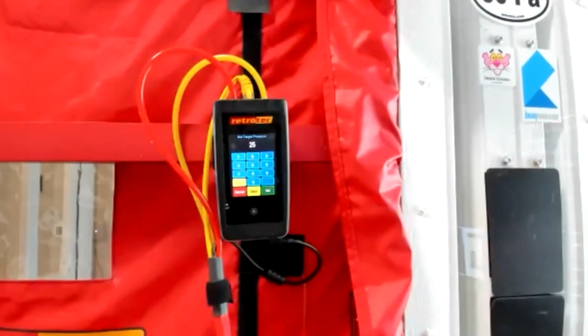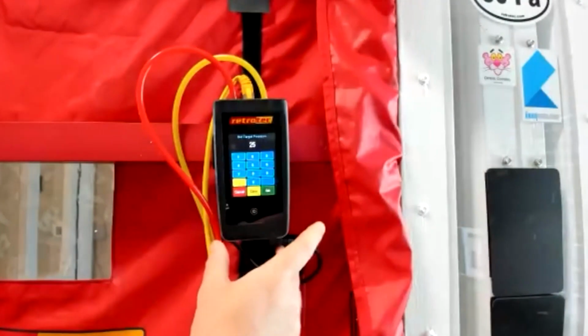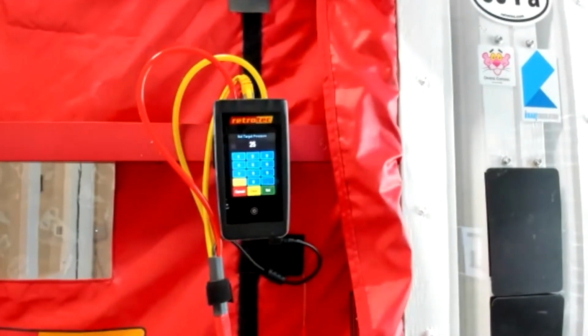Again, I want to start at 25 and then walk around and make sure nothing's getting disturbed, or I'm not noticing any funky smells or anything like that. Sometimes if you test homes that haven't been occupied for a while, the P-traps for the sinks or the washing machines or whatever don't have any water in them, so you're just pulling in sewer gas. If that happens, you'll know it immediately. It smells awful. That's happened to me a few times. So just make sure you have water in the P-traps. You can just run a little bit, fill it up. But that's another thing you might come across if you're depressurizing a house.